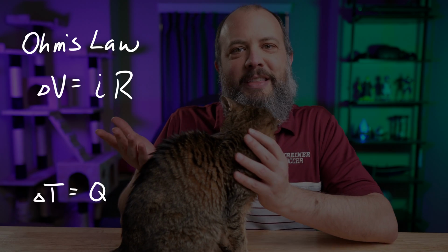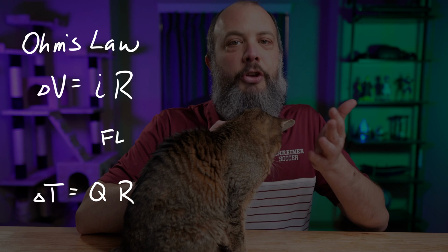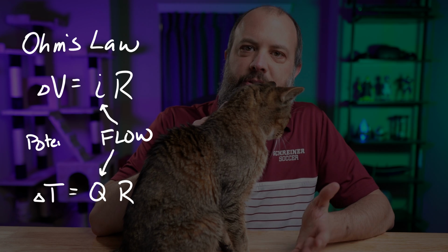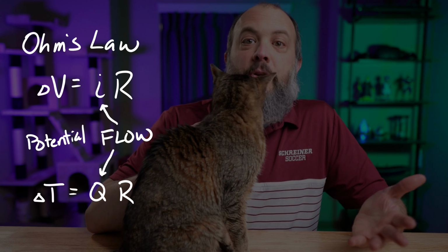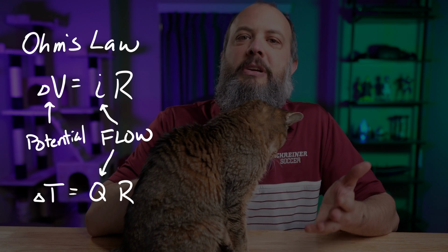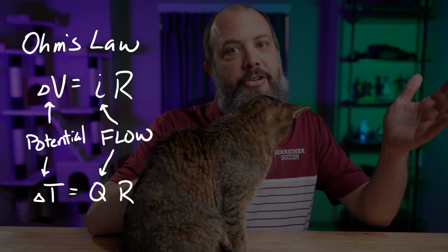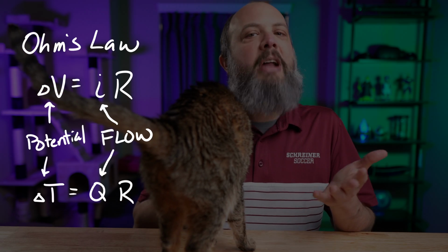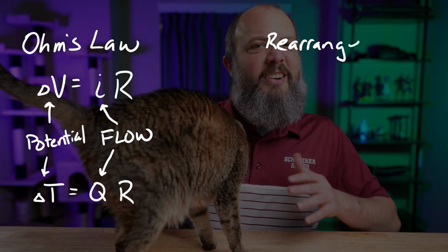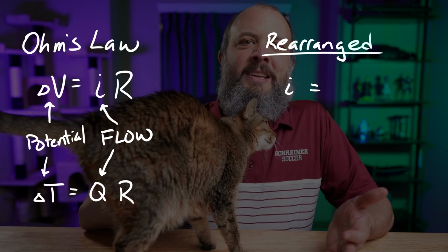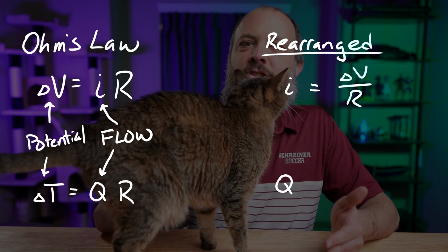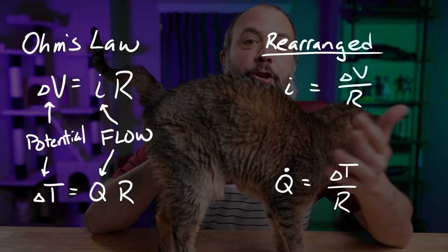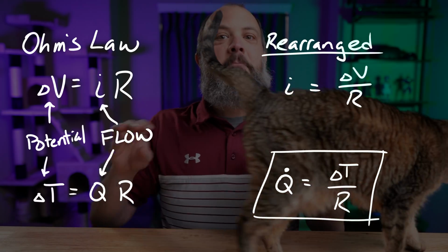In circuits, current is the thing that actually moves. In heat transfer, that's going to be Q, that's heat. And in electrical circuits, current moves from high voltage to low voltage. Voltage is like a potential. In heat transfer, temperature is your potential. Temperature is your voltage. Heat goes from higher temperature to lower temperature. And in electrical circuits, the thing that tries to slow down how much current goes is a resistor. In heat transfer, everything else in the equation is going to be your R. There's going to be lengths and areas and k and h. I'll rearrange that as I equals V divided by R. So in heat transfer terms, we've got Q equal to delta T divided by everything else.